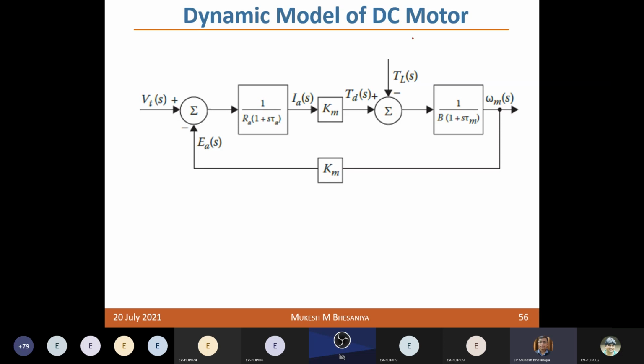It is much simpler compared to the model implemented in MATLAB or PSCAD, because those are detailed models. If you are running simulations for a longer time, it will take more time. If I'm using a closed loop control system and running simulations for 20 or 30 seconds, it takes a lot of time. So you can simplify those models with the use of these mathematical equations.